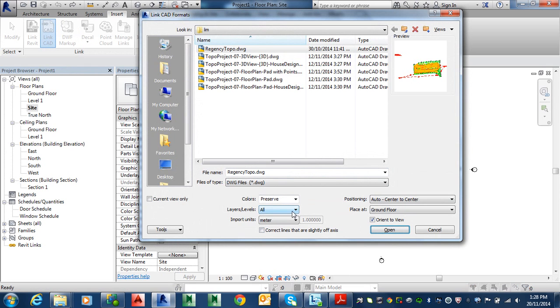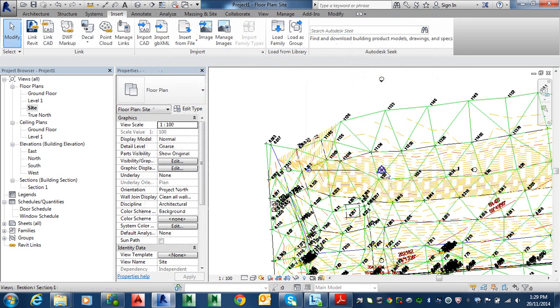By the way, here there is an option. Later on, we're going to use just the major and minor layers out of the CAD file. We do have an option here to specify which ones actually come in from the CAD file now. So we could have done that anyway, but we won't. Just leave the whole lot come in. All right, so here we go. All right, now that looks a bit better. We can see the survey points here now, which is good.